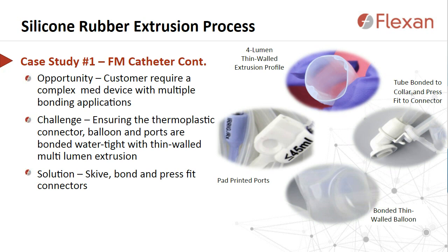There were three key challenges manufacturing the device: the complex, thin-walled, multi-lumen extrusion, the mechanical bonds for the main connector, 2 ports and balloon, and the placement of the sampling porthole. All the bonded components had to be watertight and not separate, and the punched hole for the sample port could not be deformed so that a slip-tip syringe could be introduced without any leakage. A closed system was imperative to not negatively compromise the patient.